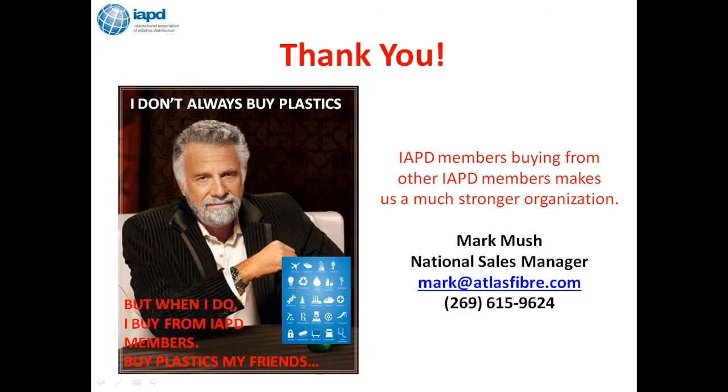Okay. To improve the tolerance by sanding, is there a specific coarseness or sanding method that works best with thermosets? You generally want a large, 4-foot wide belt sander, and there are many different grits of sandpaper to use. There are some applications where they want you to get it as smooth as possible. There's other applications where they may just want to take off that very glossy skin surface so that they can leave something with a little more bite to it so they can glue the phenolic material to some other material. So you really have to ask the customer what it is that they want.